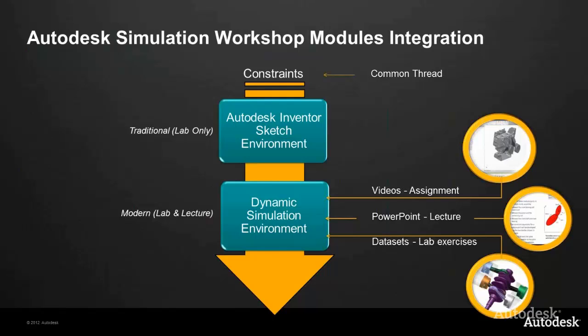can start by introducing the traditional content with an emphasis on the concept of constraints and how they control the motion. And then as you build, you just come up with different ways of writing the constraints. In the case of the traditional methods, they are primarily vector constraints. In the case of the multi-body dynamics programs, they're typically algebraic constraints.